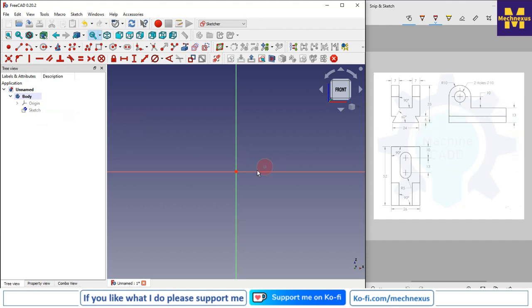And now I will draw two lines, one is horizontal and the other one is vertical. And now we will draw this R10 arc. So for this I will select the 3-point arc, and I will select this arc and line and make it tangent,